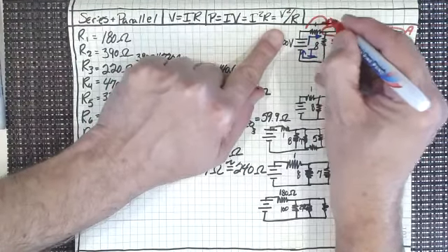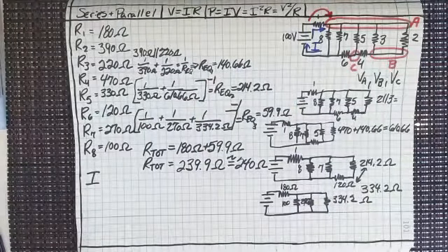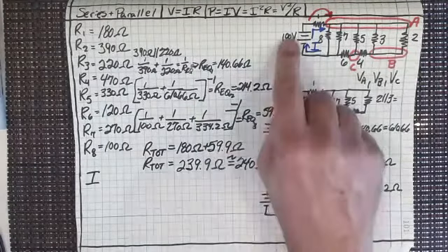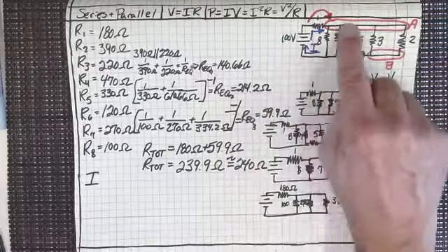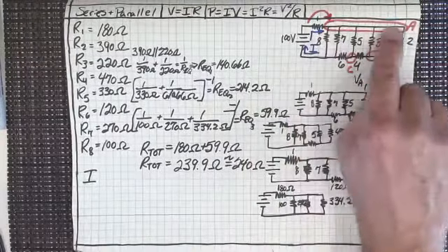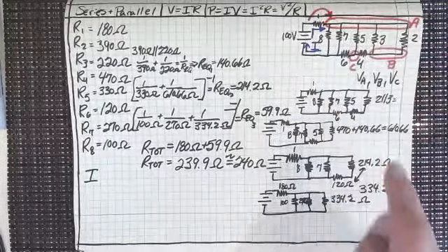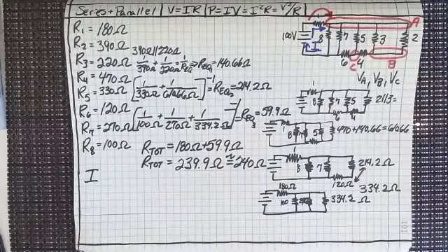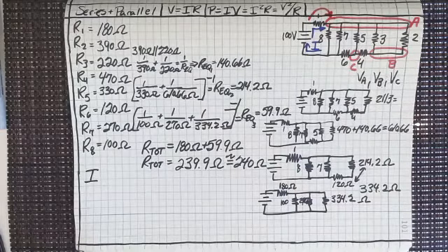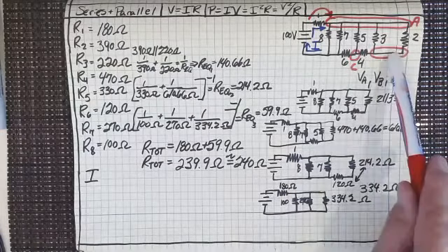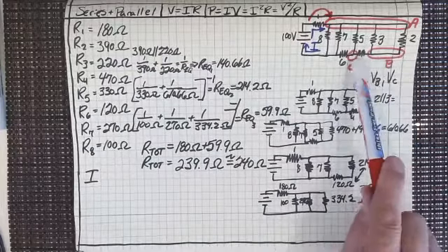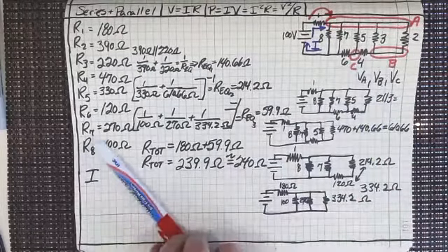If I find out what that voltage drop is across that first resistor, then I can just subtract it from 100 volts, and that tells me for the top of all of those resistors that are up there, what their voltage is going to be on that side of the resistance. And very quickly, that will help me decide what the voltage is at B, and then that will help me decide what the voltage is at C.